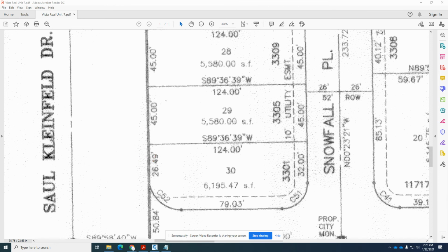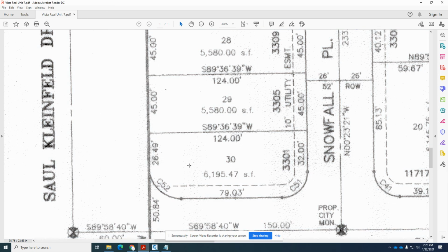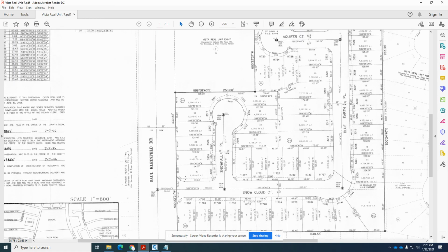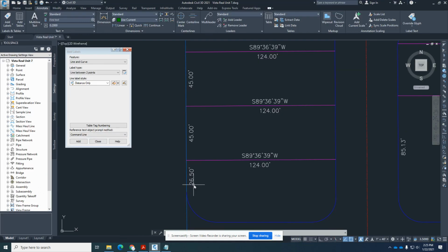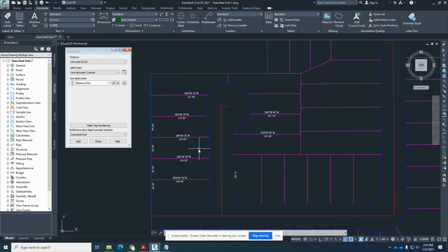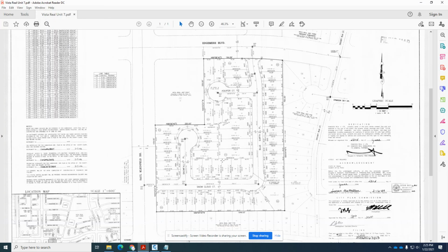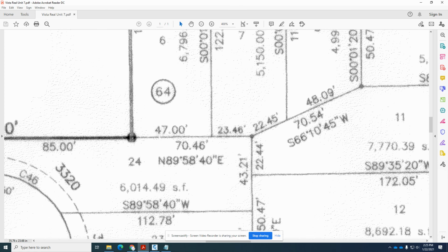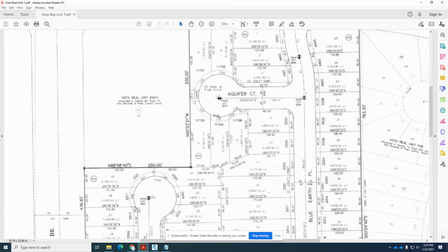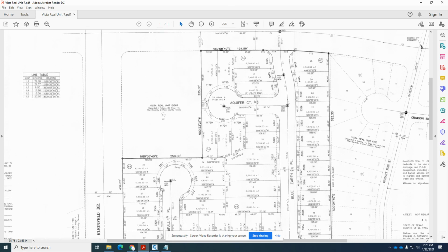It's just because of the nature of Civil 3D plats in civil engineering plats that there is an error of up to 0.03. Remember, if it's more than 0.03, you did something wrong somewhere. Hopefully that's not going to be the case. That's how you do your distance onlys. Now take a few minutes to put in all the distance onlys. They're all over the place, ladies and gentlemen, so take the time to do those for me. The next one, I'll talk about the next label style.